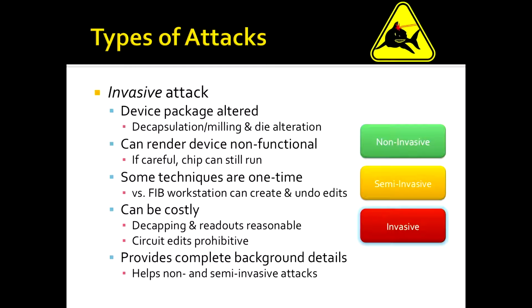So you can use all the floor plan data. You can actually force certain transistors or buses, circuit nets, on and off, and get a good idea of how the device operates. And then you can feed this information back into the semi-invasive and non-invasive attacks to make them a lot easier, because you know where on the chip to target.